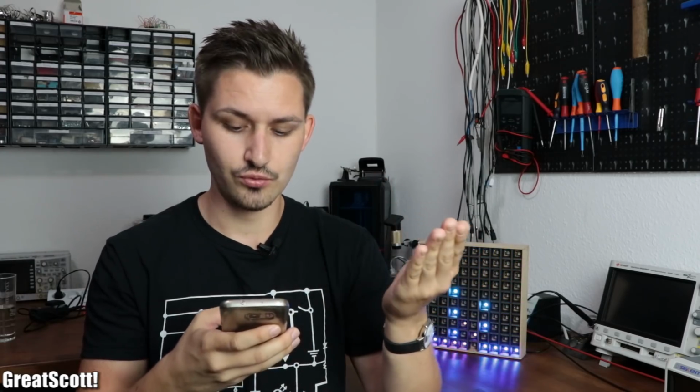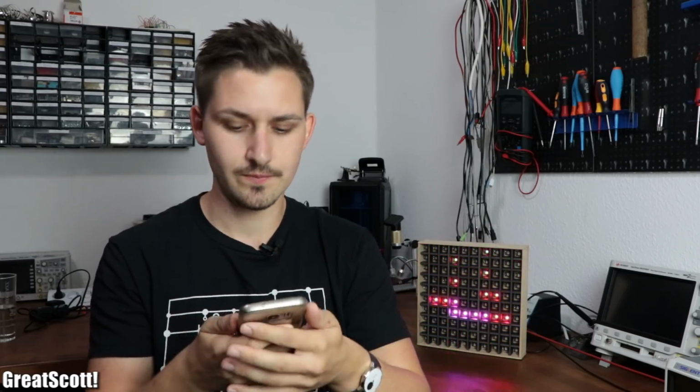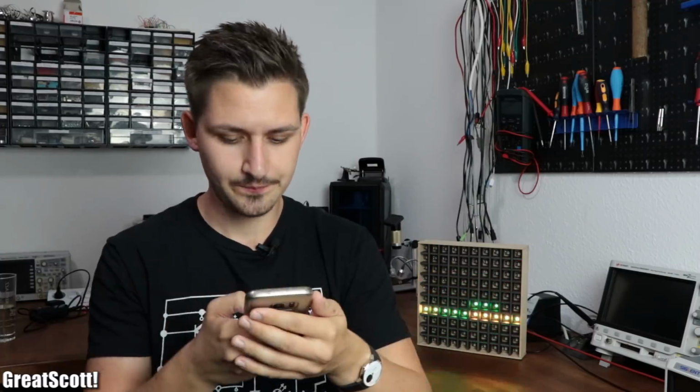So that's what I would do. Just 4 in series, buck converter, BMS, balance connection put to the outside so you can charge it up with a balance charger. That's how I would do it.